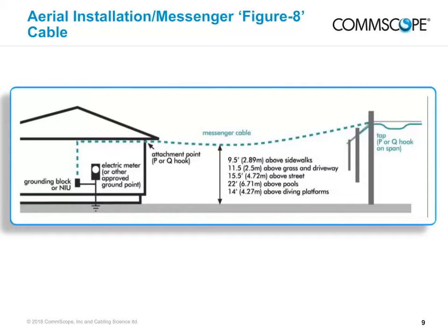When installing powered coax cable carrying up to 150 volts, pay special attention to the cable-to-earth distance as shown in the diagram. NEC 830 also requires that cable attached to the building within 8 feet or 2.5 meters of grade must be placed within conduit, raceway, or some other approved cable guard. NEC 830 installations will terminate at an NIU. Most NIUs have built-in connections that must be grounded at the meter or other approved point.